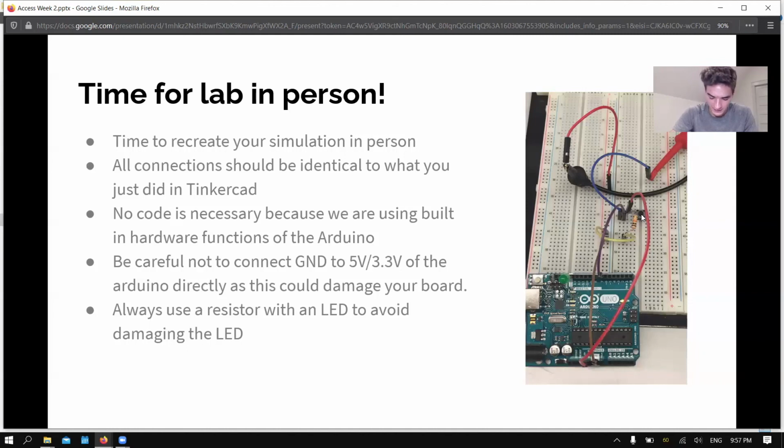And then I'll take my Arduino and my final 2 wires, and I'll have a red wire going from the 5 volts on the Arduino to the positive on the board, and then a black wire from ground on the Arduino to the negative on the board. And then I'm going to plug it into my laptop and hope it doesn't blow up. Okay. Just kidding, that won't happen, so yeah.